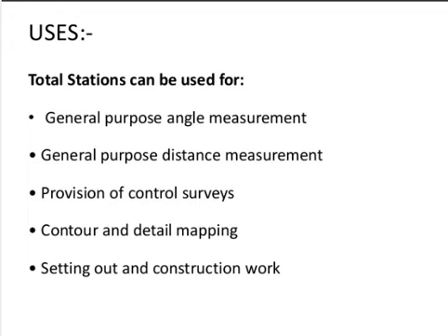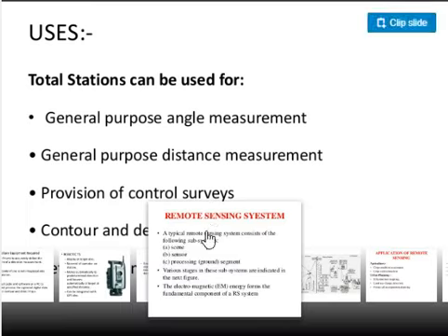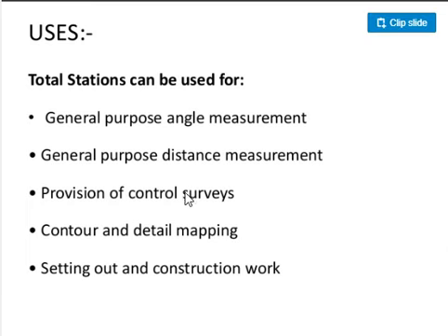If you want a factory 250 meters inwards from the boundary, the 250 meters distance can be measured with a tape. But if you know the point X, Y, Z, and have it tabulated along with you, you just take some readings and give one click of a button. It takes just 15 minutes rather than a whole day to locate the corner of the building. So it is mostly used in construction setting out works and detail mappings.